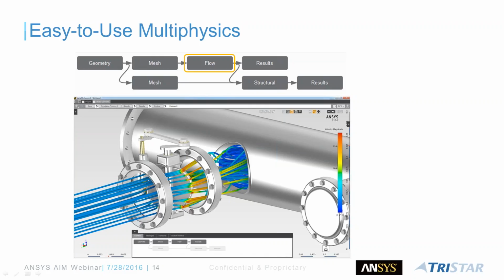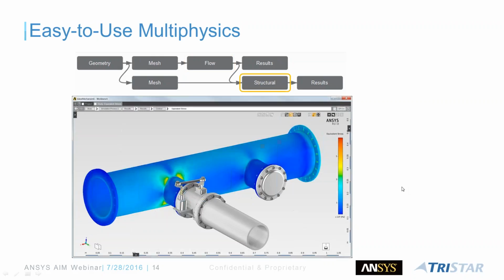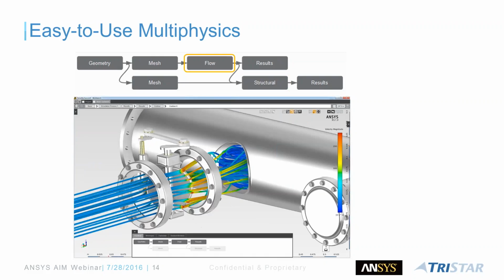And you can do this with a one-directional fluid-to-structure interaction, which is needed in quite a few designs, like in this example here. I may be interested in the fluid flow of this assembly, but I'm also interested in the stresses and the deflection on the components, right? You can see that the structural results give you the stress plot, what you're seeing on the screenshot, and this is giving you the fluid flow, right?